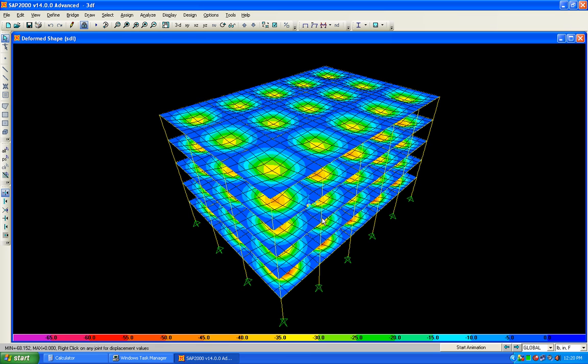And check the deflection. The deflection is minus 65. Let's check the units. It is basically minus 65 into 10. Okay, the 10 inch slab is not okay. We have defined 10.833 inches, so we need to correct this.